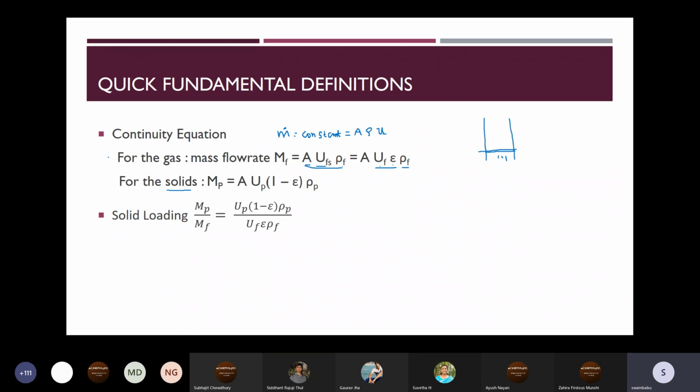The first one can be used, but the second one cannot be used for fluidization, because the particles are limited to a certain height, they will not move like a fluid continuously. Hence, the bottom expression we will not usually write for fluidization. This is only for pneumatic transport. The other one can be used for whatever condition, because the gas is moving continuously.